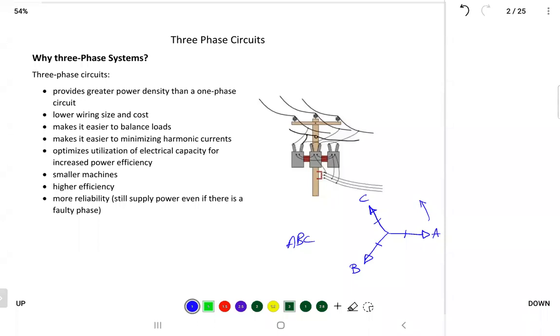The sum of a balanced system like that equals 0. Well, let's just prove it. First, you add A and B, because I want to prove that A plus B plus C equals 0. Somebody might ask, is it voltage or current? It doesn't matter, voltage or current. For balanced voltages or balanced currents in a three-phase system in positive sequence, the sum should equal 0.